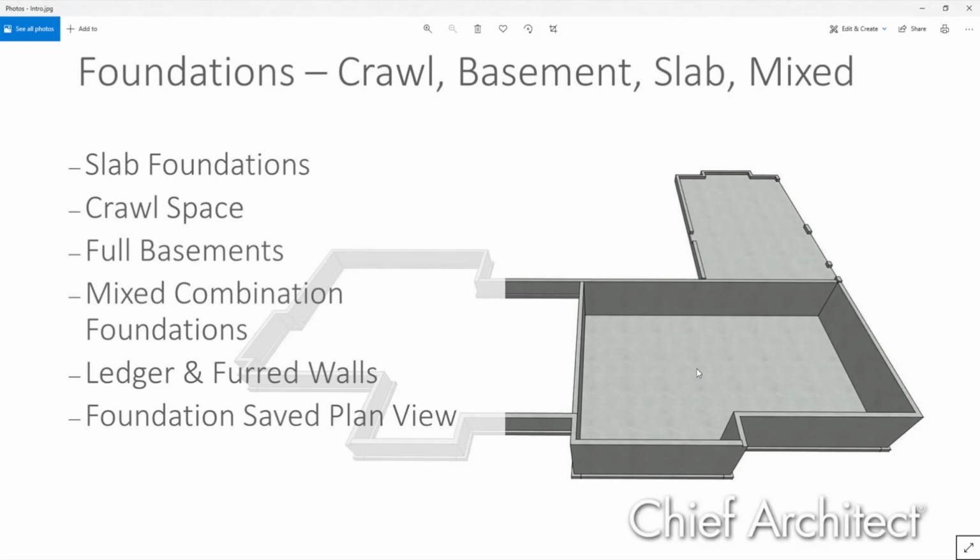Hi, in coastal South Carolina, we have a situation similar to Houston, but typically we do a 16-16 CMU filled column with a 24 by 24 footing, but we have to have a 12 by 12 continuous footing between the 24 by 24 footings. Is there a way to draw that? So you can make your footings any width you want. If I understand your question correctly, Charles, you have maybe a certain wall that has a thicker or wider footing.